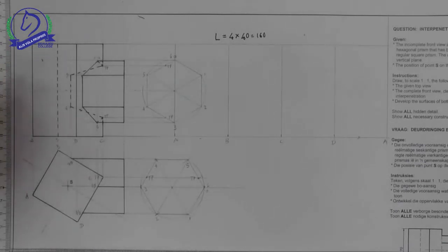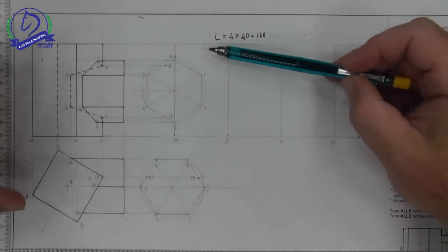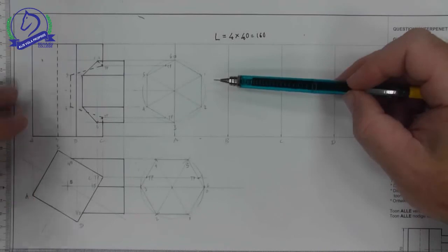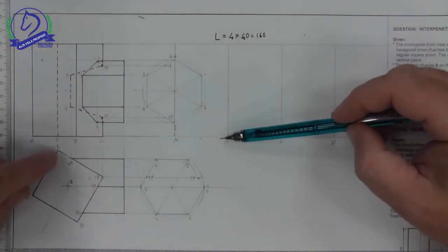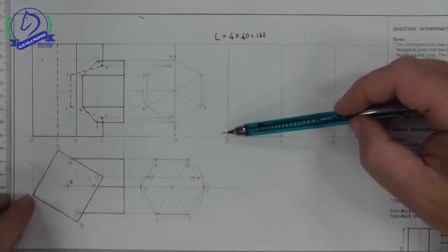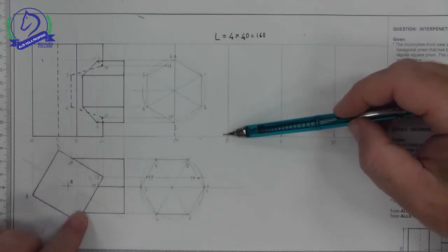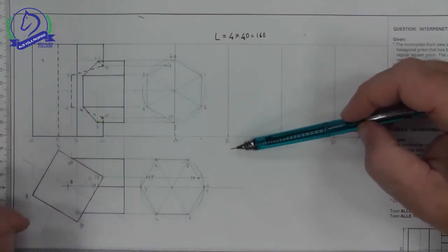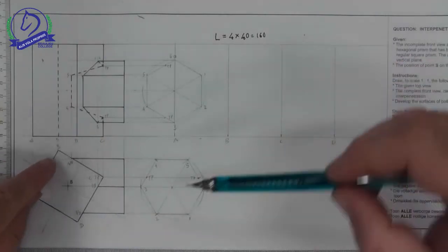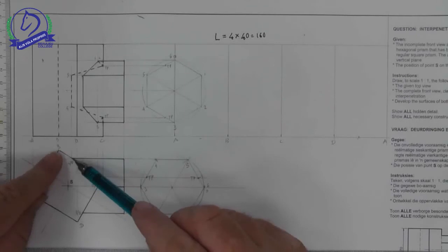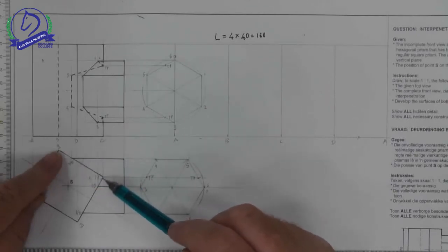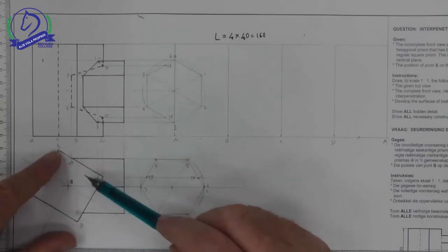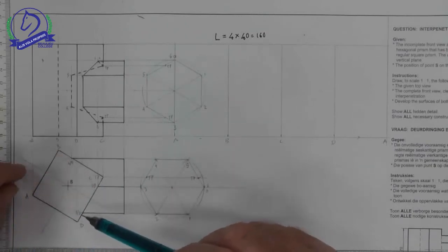What we need to remember when we're doing our development is that we can't take all the measurements off one drawing. So when we have folded our branch pipe out open, we've used the measurements from the top view. So we now need to go to the front view to get our height measurements. Any other measurements we also need to take off the top view to find where point 4 and 5, 0 and 3, and 1 and 2 are. We need that off our top view.